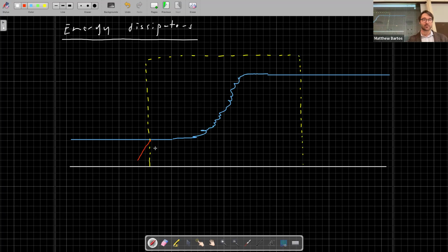And we have our hydrostatic force at the upstream end and at the downstream end. I'm going to call this FH2. This is FH1 at the upstream end. And we have, again, our momentum flux in, m-dot 1 times u1, momentum flux out, m-dot 2 times u2.